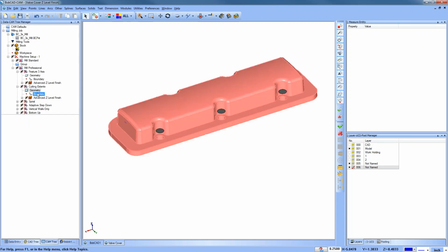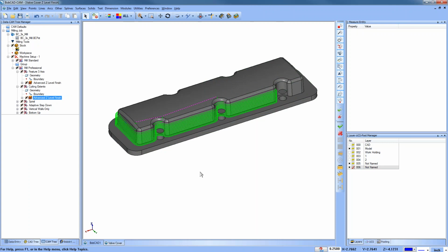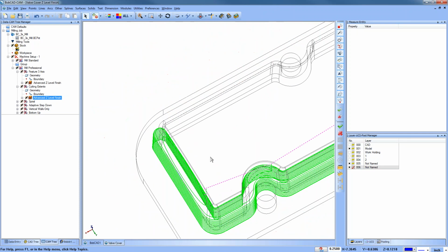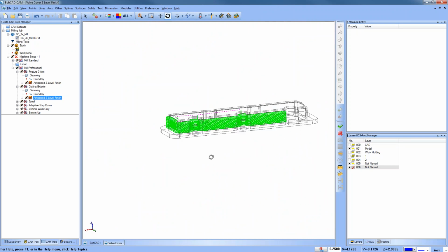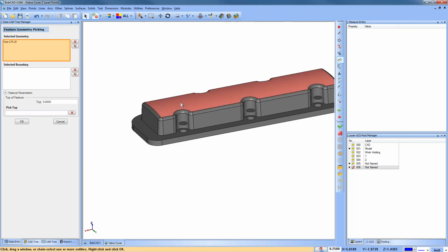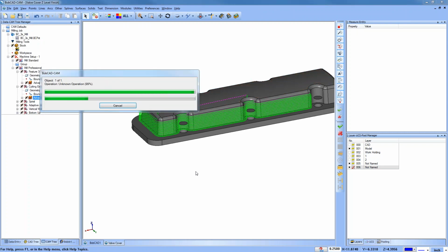The reason why I wouldn't do that is when you select just a few of the surfaces, only the surfaces that are selected are used for gouge protection. So what's going to happen is the toolpath's going to run around that surface on both sides, and that doesn't make any sense, okay? So for new users, I generally recommend selecting everything, but if you're a more advanced user, you can choose to select specific surfaces, not selecting everything.